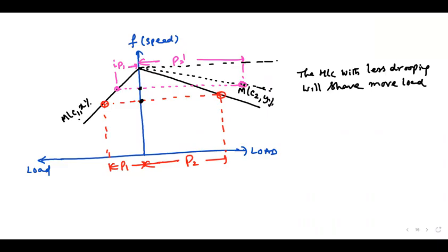Tell me. Sir, in any situation, case 1 or case 2, if there is a rise in the excitation or the mechanical power input, then there will be a synchronizing current in the loop. After settling the terminal voltage at a particular level, is this synchronizing current still present or not, sir? Will it go to zero or remain in the loop? No. It will exist.